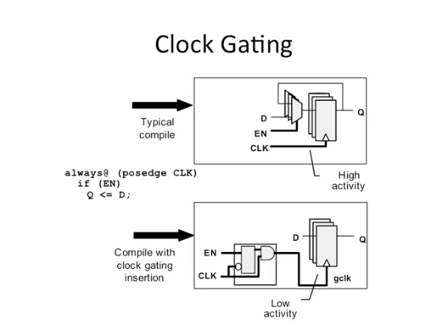So the clock power in synchronous design is the dominant dynamic power. Also, the activity factor of the clock net is typically the highest. It's basically two, since there are two transitions per cycle. So a lot of effort and attention has gone into how to reduce the clock power. One technique which is used is called clock gating.